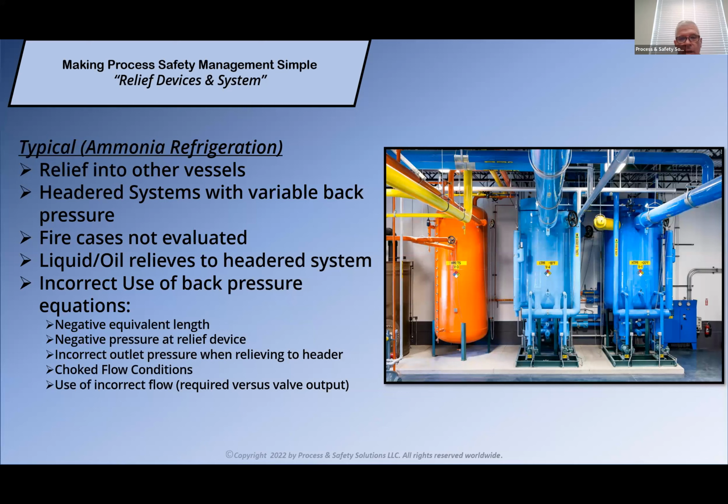Fire case is not evaluated. For example, if you look at this picture to your right, there are 3 vessels sitting there. All 3 vessels could be subject to a fire. So now we have 3 vessels that are relieving essentially as that fire has taken place. Now we know for the most part in a fire case, the relief valve will open and close as that pressure builds and et cetera. So not all of them may simultaneously be relieving at the same time, but you could have 2 of them relieving. Well, when the other one built enough pressure, there's going to be back pressure on that relief valve, not allowing that relief valve to lift as it should at the right pressure as well.